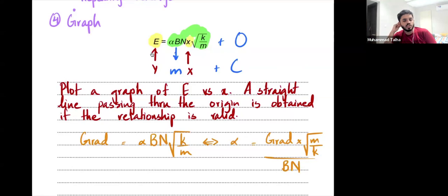You should just know, Osman, when you use what sort of a length measurement instrument, right? For example, the diameter of a really thin wire, I would use a micrometer. Maybe if that length is slightly larger, I would probably use a vernier caliper. But the special use case of a vernier caliper is when I want to take some internal measurements.